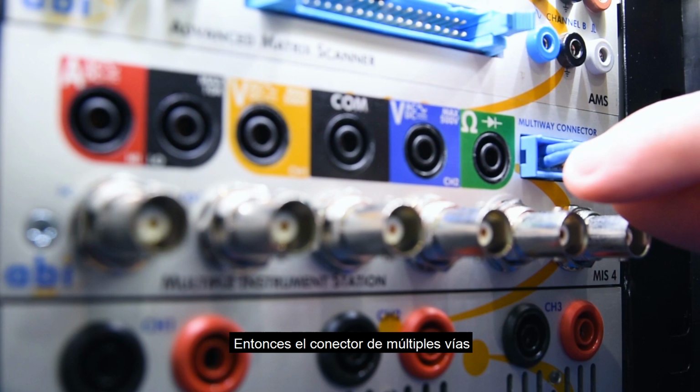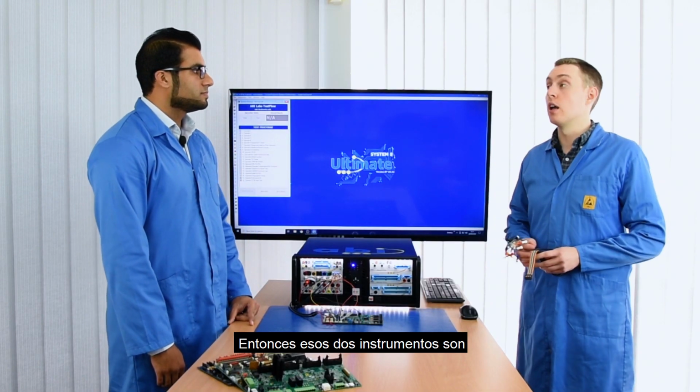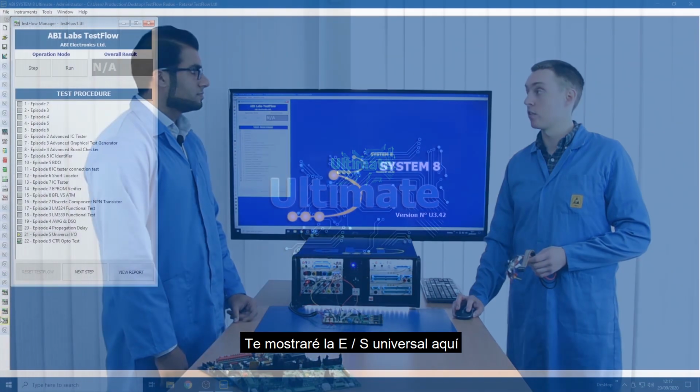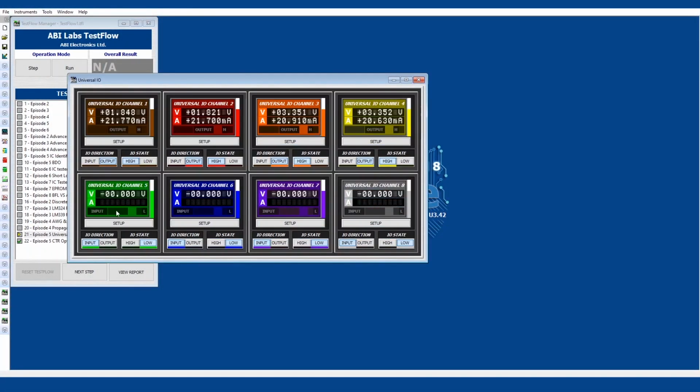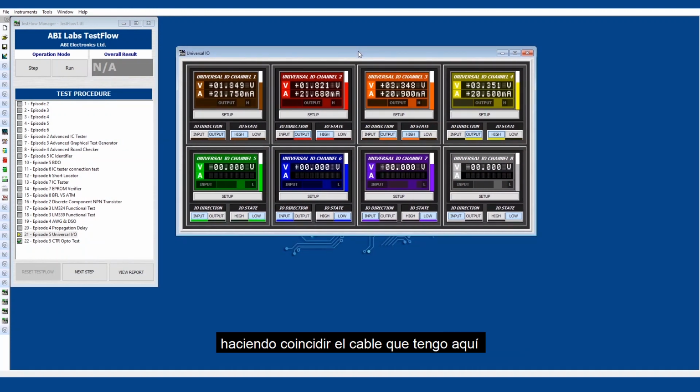So the multi-way connector can use two instruments with the MIS4. Those two instruments are the universal I/O and the auxiliary power supply. I'll show you the universal I/O here. In this instrument, we've got 8 channels, all of them different colours, matching the cable I've got here. You can either set them to input, output, drive or sense, and you can either set them as high or low, and you can choose what high or low levels you want in the settings.